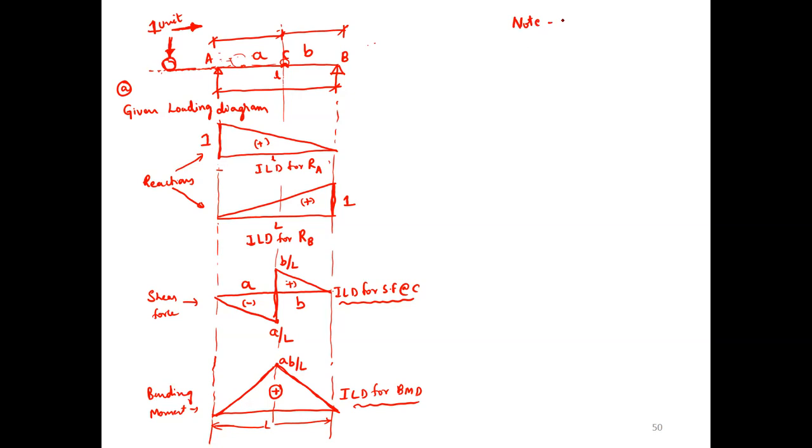Note: generally you are getting point load and UDL only. It is not applicable for UVL. This particular ILD concept is applicable only for point load and UDL. If a couple is given, you have to split the couple into two opposite-direction forces and then solve.